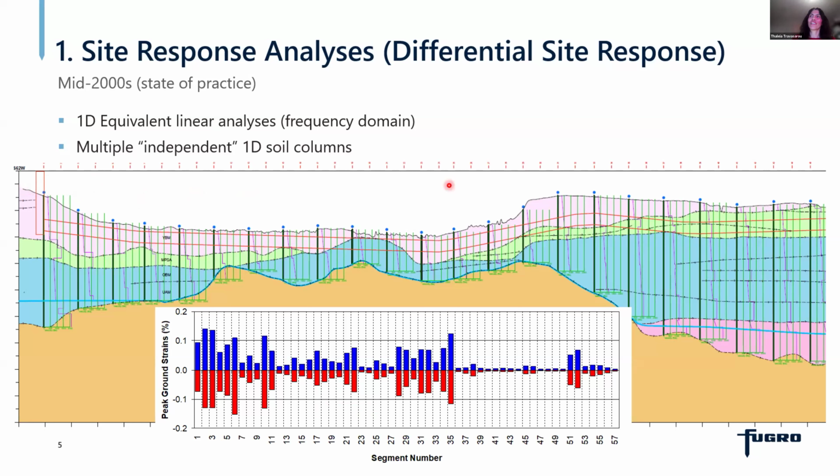You're touching on a point that I was not going to present on, where there is scour behind the island and around the tunnel, and there was an area of slope instability and additional demands, but I was not going to touch on that for this. Also, that is one of the most famous cases of site amplification, because Yerba Buena Island is a rock outcrop, and just close to it there is Treasure Island, which is reclaimed land. So different levels of acceleration there are very important. Exactly, yes.